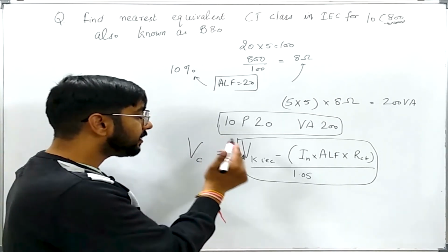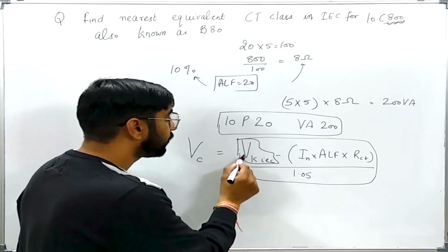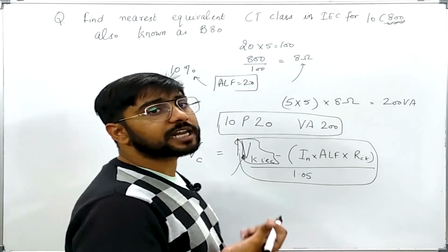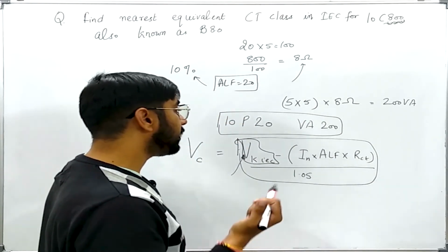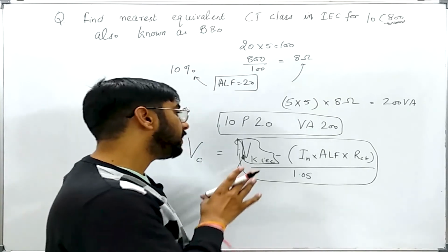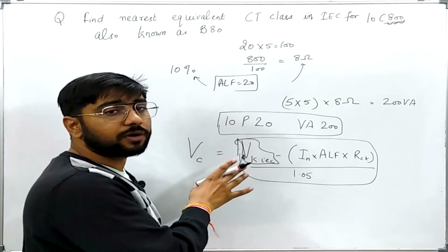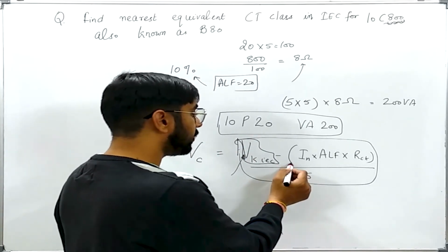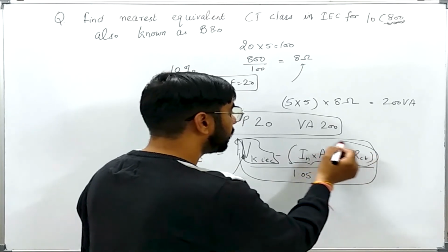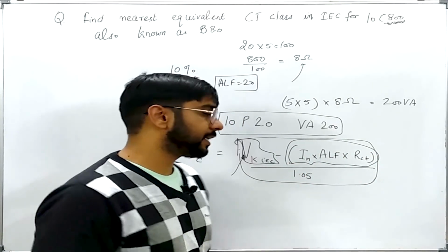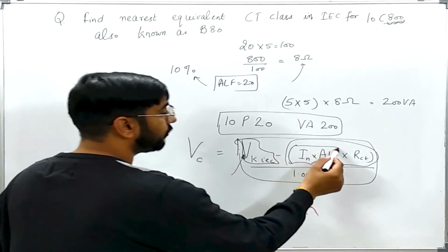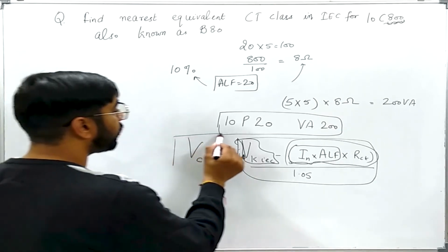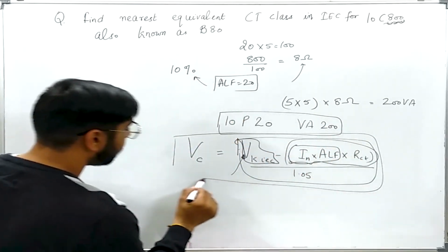That is, this cannot be actually measured because there will always be a current flow whenever we connect any meter, but terminal voltage can be measured. Okay, so IEEE and IEC have this difference also, that IEEE always gives the terminal voltages, IEC gives the induced voltages. That's why I have subtracted the value of the drop in the resistance of the CT secondary, at the maximum value of the current when saturation will be there. So in this way we calculate the knee voltage in IEC and IEEE.